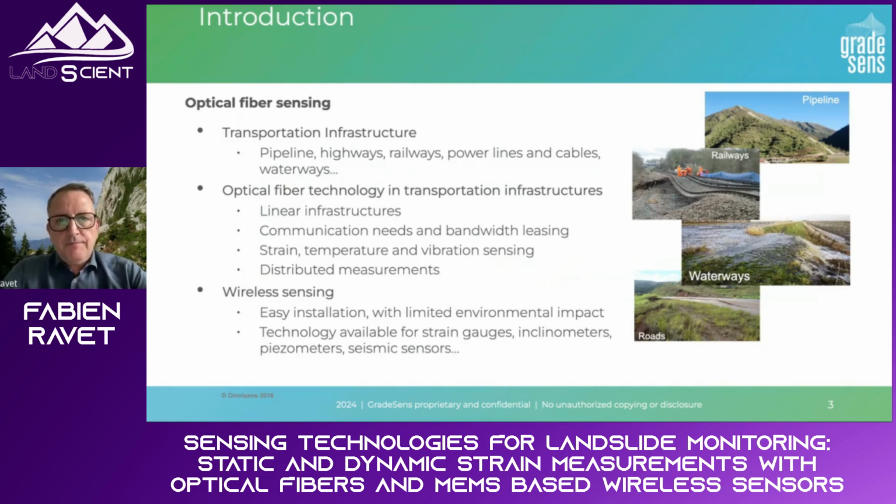The interesting thing is that if we know about the physics in optical fibers, it's possible to turn them into strain, temperature, and vibration sensors. And what is even more interesting is that you can make the sensors continuous. That's why we talk about distributed measurement or distributed sensing, meaning that we have along the optical fiber thousands or hundreds of thousands of microphones, thermocouples, and strain gauges. It's just an image, to picture a little bit what I'm talking about. It's really like having a sensor every 1 meter, but it's not a physical sensor attached to the fiber. No, it's the fiber itself that is the sensor.